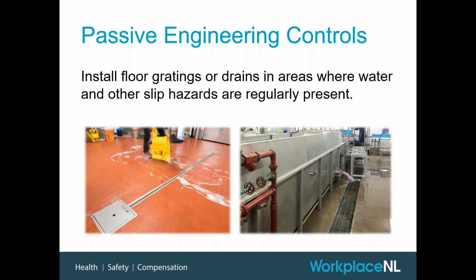And it's better to drain those directly into a piping system, but where that's not an option, if they are going to be draining out into the building, to have them drain directly into a trench is the way to go. And having that type of grading that's sitting on top as the flooring allows then for water and any other kind of debris to fall into that drain.